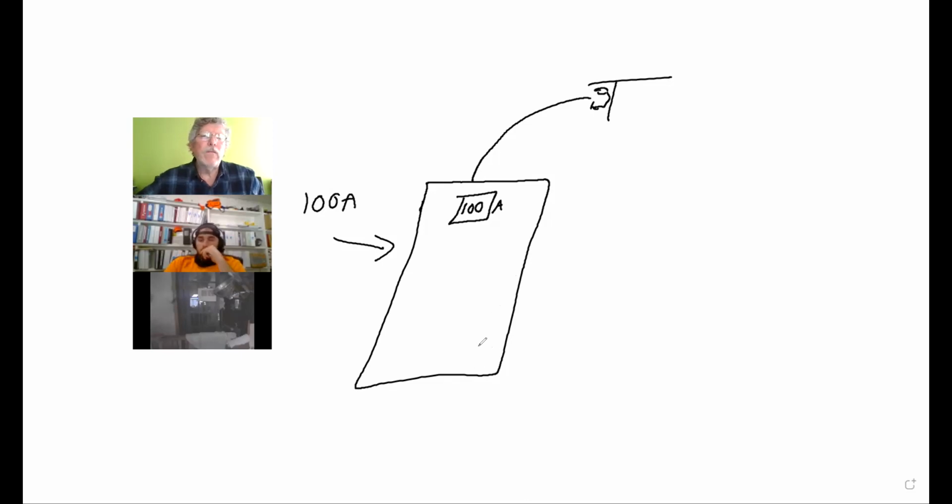Now we want to come in with a solar array and we always come in and make our connection as far away from the main as possible. So you would want to be either on the bottom right-hand corner of the panel or the bottom left-hand corner, as far away, and that's usually where the empty spots are going to be anyway. So that's where you want to come in.